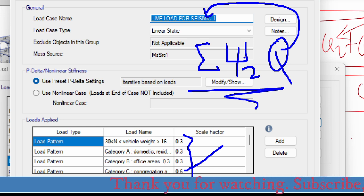So for my case, phi 2 equals 0.3 for all variable loads. That means I have applied 3 variable loads: floor live load, live load at roof, and live load for parking. For all 3 load types, I use a reduction factor of 0.3. Okay, this is for live load for seismic one.